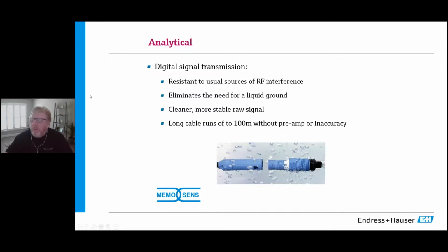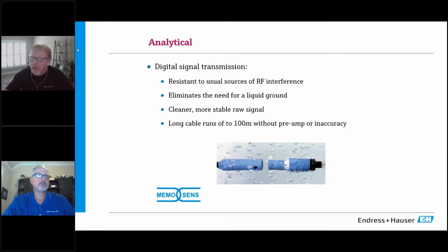So we're basically charging that through this inductive coupling, if you will. Because it's low powered and it's digital, we were able to give you much longer cable lengths, up to 100 meters or 300 feet. With the old analog sensors, you are limited in how far you can have the sensor from the transmitter. So again, with our platform and this MemoSense technology, greater flexibility for the end user.